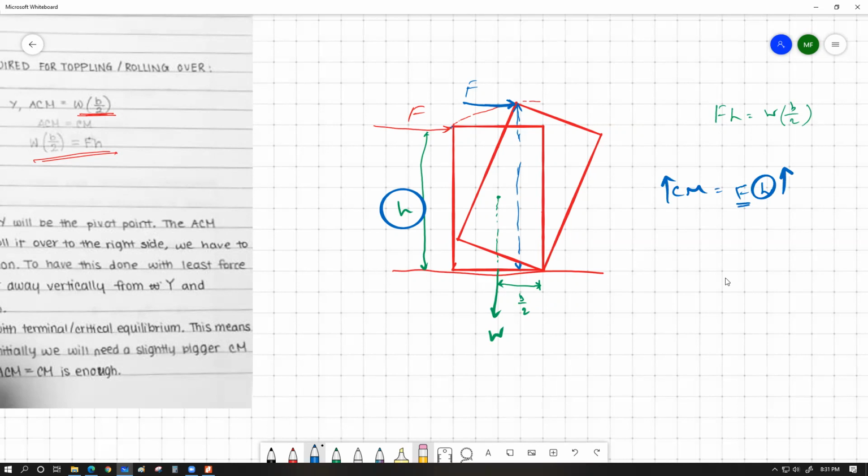However, what happens to the anti-clockwise moment, which we are trying to balance? What is happening to the anti-clockwise moment that we are trying to balance? As the object starts to roll over, you should understand, let me draw this with blue once again. The center of gravity of the object will also rotate about this. For example, whenever the object is in the tilted condition, let's say the center of gravity is right over here. I'm trying to approximately get the diagonal cross point.